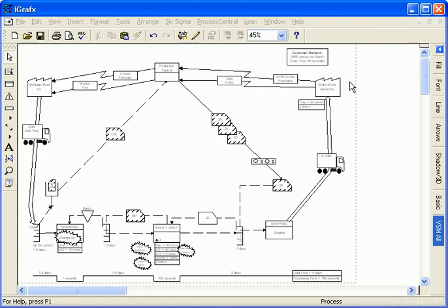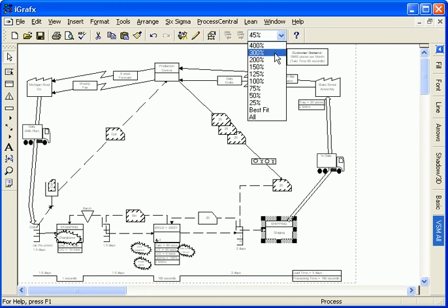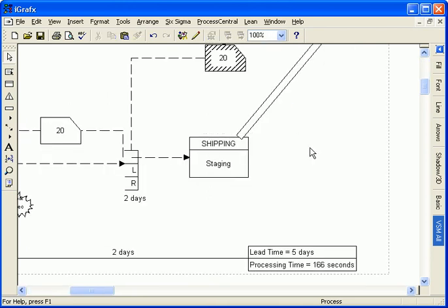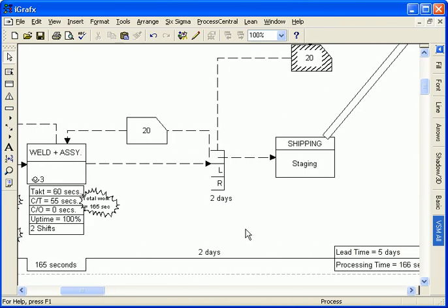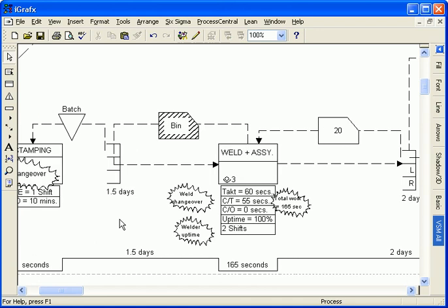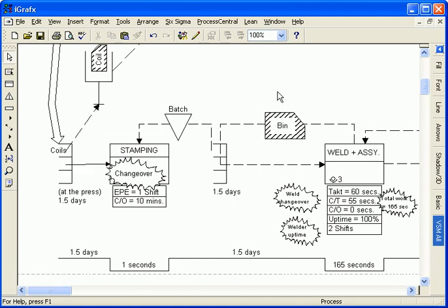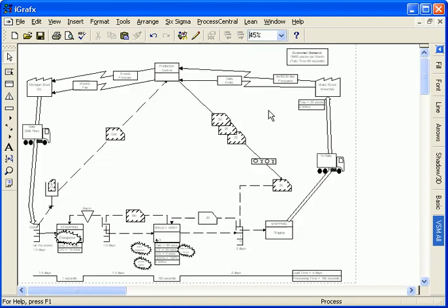After analyzing my current state diagrams, iGraphics provides the shapes and tools required to build future state EVSM and VSM diagrams that reflect the improvements identified. For example, in a future state VSM map, supermarkets often replace push flows. Also, Kanban symbols and Kaizen work bursts are frequently used. In summary, iGraphics provides all the tools and benefits lean practitioners are looking for in a value stream mapping tool.